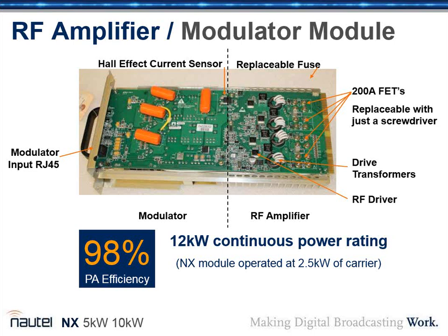So in other words, in a lot of other designs, these would be ganged up. These two would be driven by the same signal, and those two would be driven by the same. We're actually controlling them independently so that we're sure the switching does not occur when there's voltage across it. Is that right? Yeah, there are pairs of transistors that switch together, basically, but each side is controlled separately.